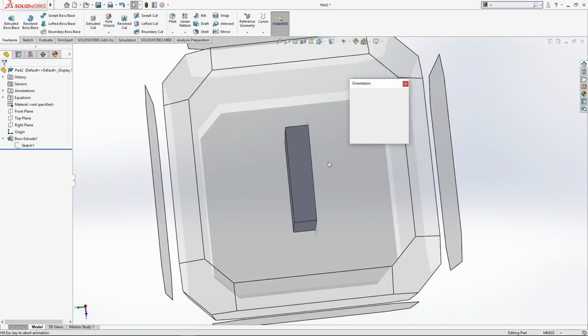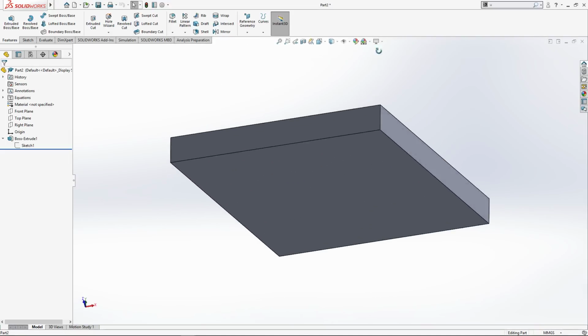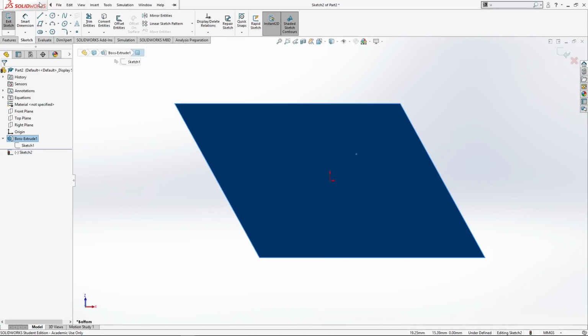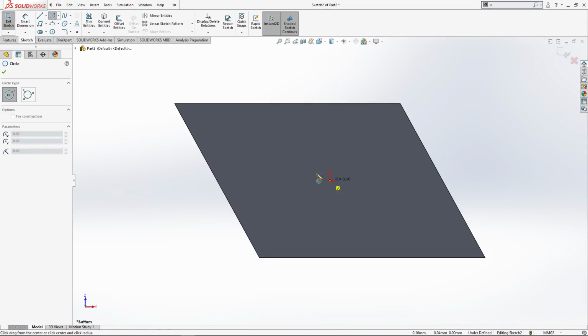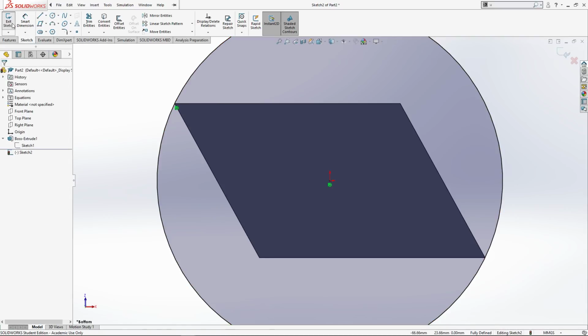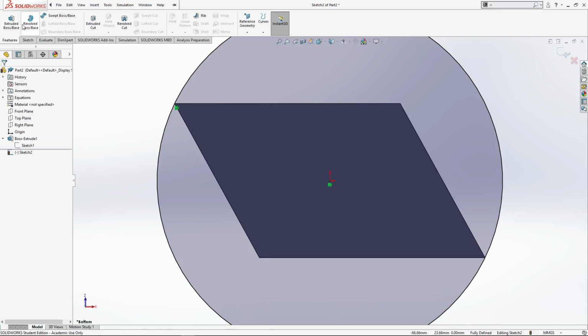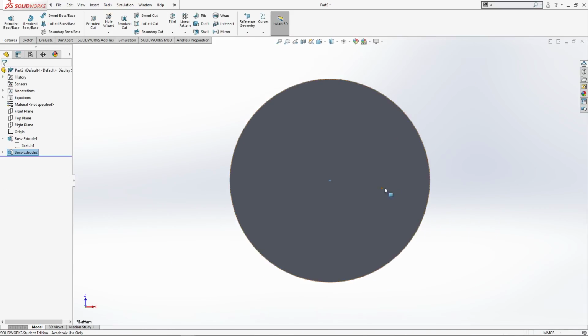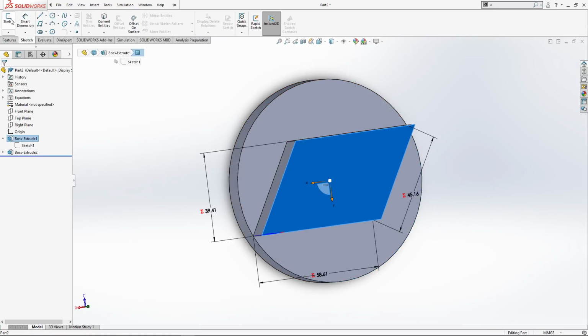It's kind of like the thing before. So I'm going to go ahead now, go on the back plane, sketch, same thing as before. I'm just going to sketch this circle, make it coincident here. Perfect. It's fully defined. And feature extrude. I'm going to make this equal to CI extrude. Perfect. And then I'm going to make this slot, sketch there.